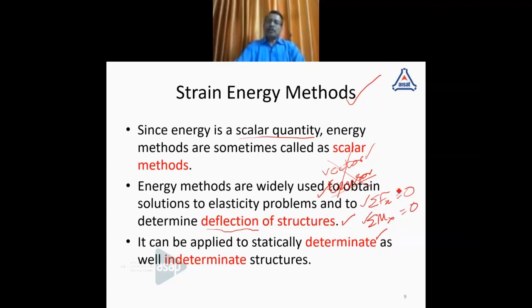And if you are able to solve a problem using any of these methods, we can call it a statically determinate problem. And if it is not possible, then we call it statically indeterminate. That is, using the principles of statics, we can solve the problem in a statically determinate case. In the other case, it may not be possible.